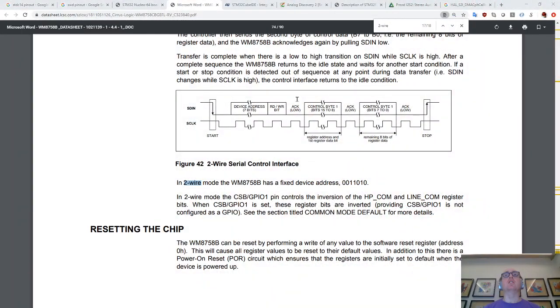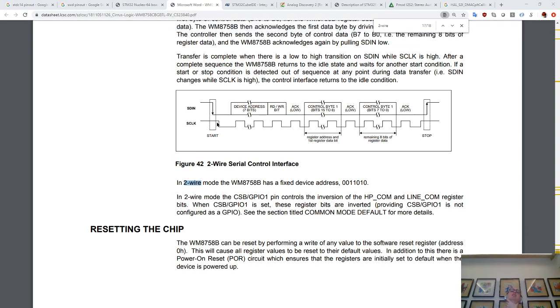So this is what I2C looks like. Basically, to talk to the codec, you need to bring the data low while clock is high. And again, I could have used the HAL I2C library if I hadn't missed off the pull-ups. So you pull this low, that's called a start condition. You then feed it 7 bits, which it documents only in binary in this data sheet.